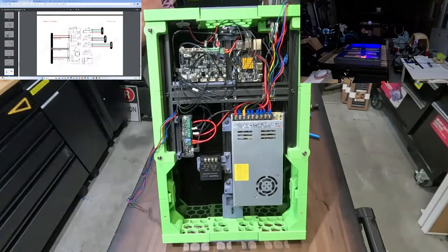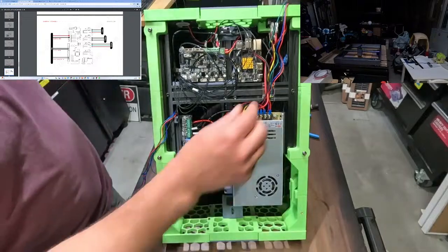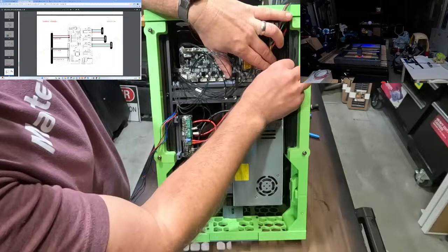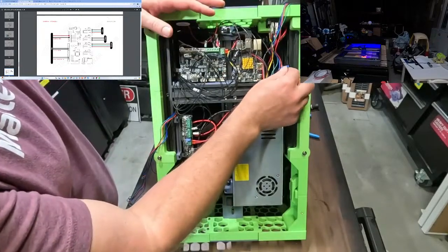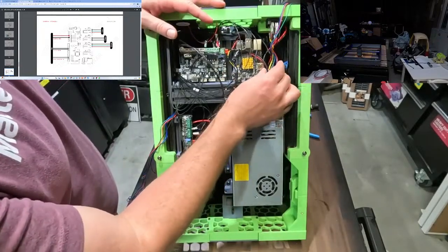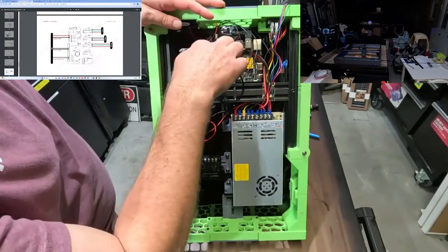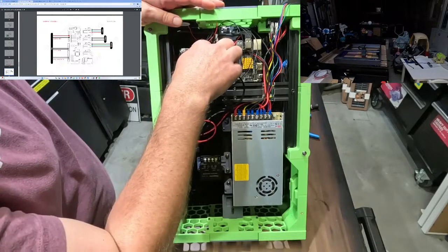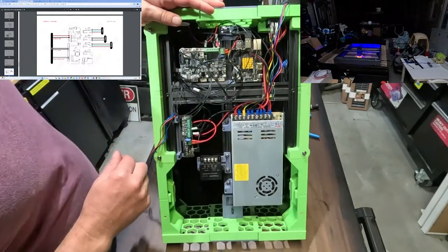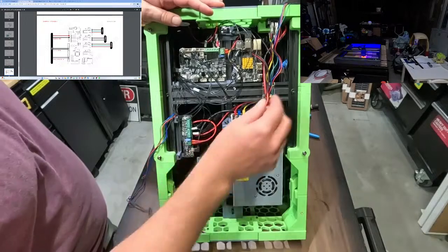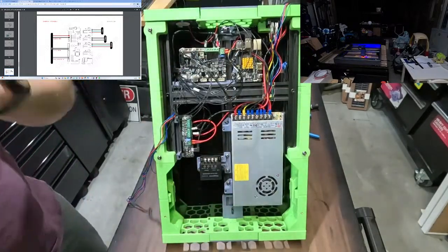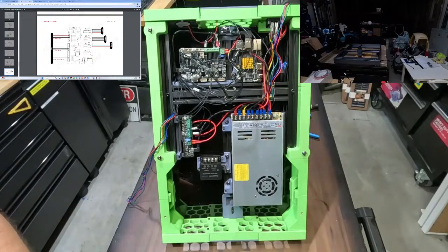If you recall, a couple of videos ago, I pulled the end stop and the cable for the heated bed assembly through this port, and the cable isn't long enough because it has to make it all the way over here and go to the main control board for the bed heater and the bed sensor. Those two cables are not long enough, so I may have to rig up some extensions to get them over there with the appropriate gauge wiring.